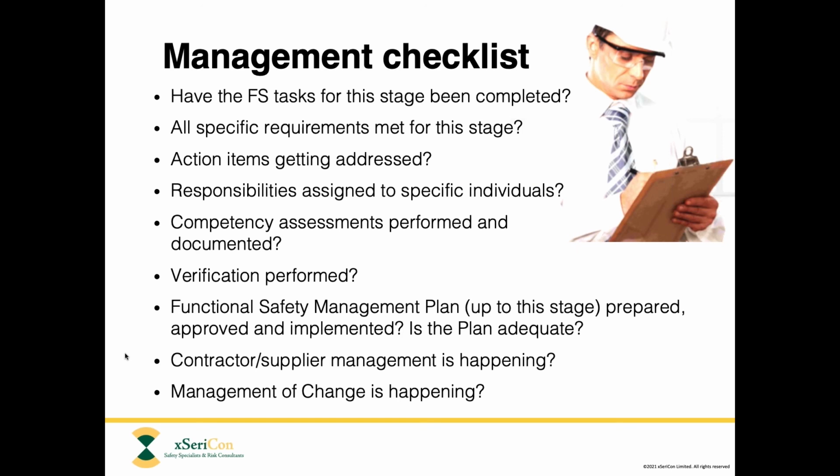We would like to see your functional safety management plan. The plan does not need to be complete right from day one. It can grow as you work your way through the life cycle, but at least we would like to see that the parts of it that need to be in place up to the stage that we're now reviewing are fully completed and approved and getting implemented, and that you have your plan in place ready for the next phase of the life cycle.